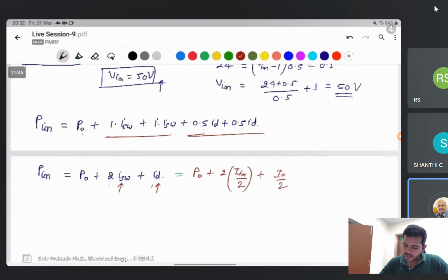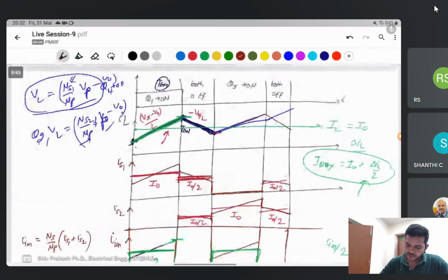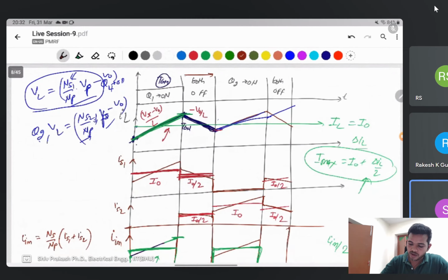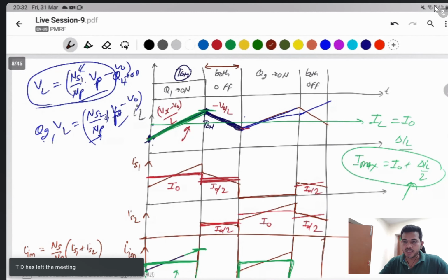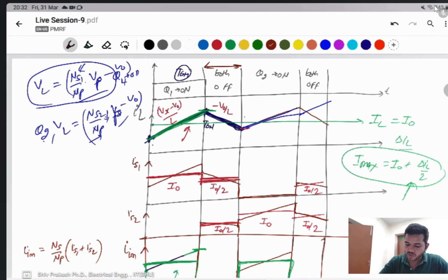The dead time I provide here. This one is when both switches are on-off at that time. Then dead time is not a big issue here because you provide off time. One switch is on, then off time or total off, and after that the second switch is on.